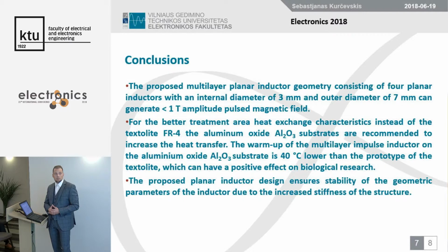For better treatment area heat exchange characteristics, instead of textolite, aluminum oxide substrates are recommended to increase the heat transfer. The warm-up of the multi-layer inductor on aluminum oxide is 40 Celsius lower than the textolite prototype, which can have a positive effect on biological research.